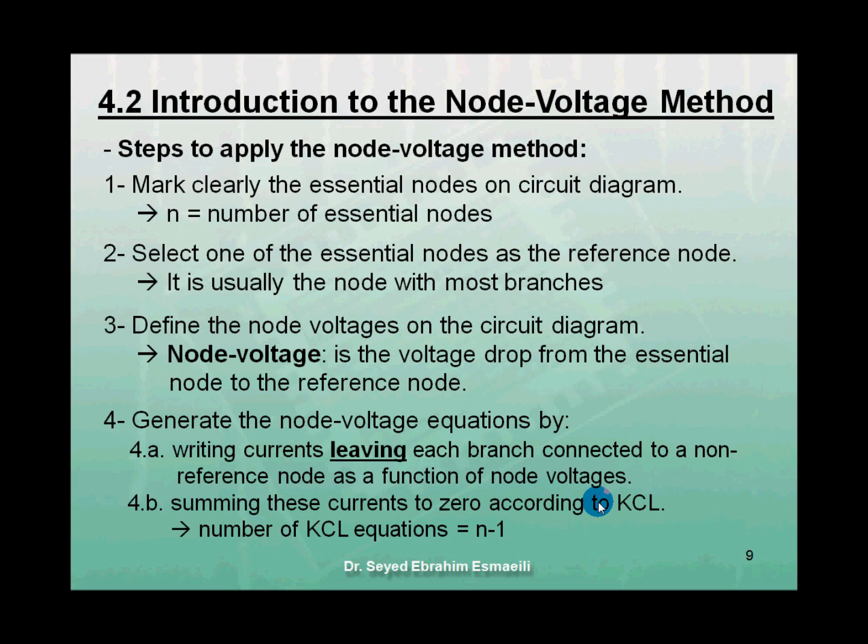In this part of the lecture, we will learn about one of the most powerful techniques in circuit analysis, which is the node voltage method. The steps required to apply the node voltage method are the following. Mark clearly the essential nodes on the circuit diagram. N equals the number of essential nodes.